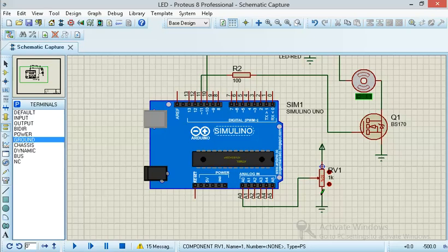It won't work again. So it can't tolerate more than that. If you are using a 3.3 volts Arduino board, whatever input you are passing into the board must not be more than your supply voltage of the Arduino. It must not. So keep that in mind.